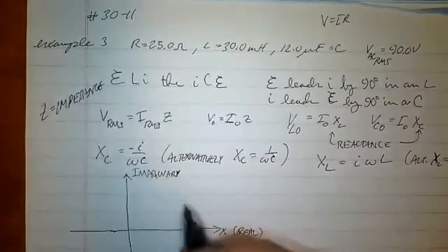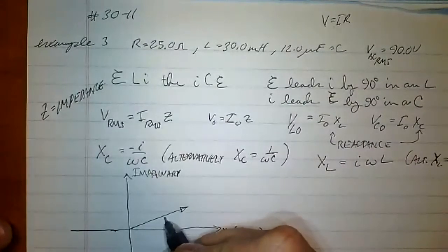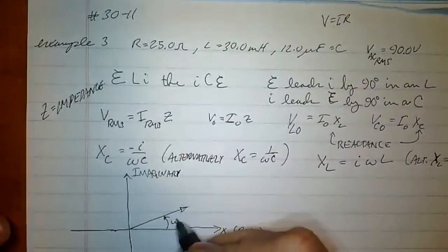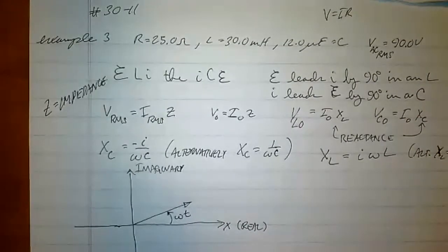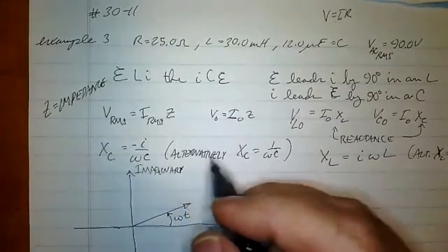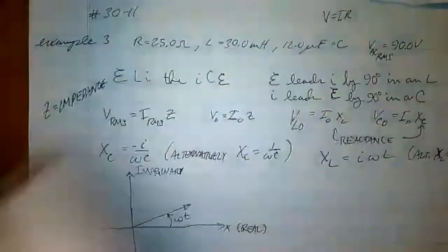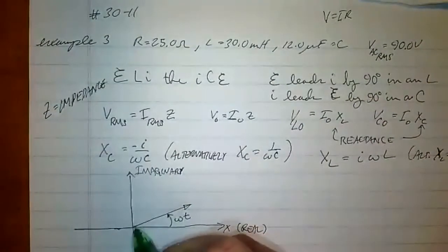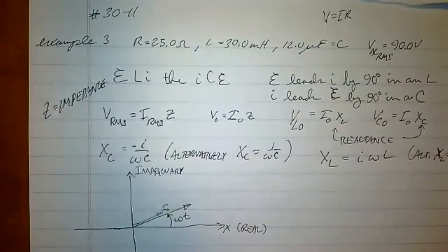Now, after any time t, this phasor diagram has rotated by an angle theta equals omega t. Now, this quantity right here, you could interpret it a couple ways. One, let me do a different color, I'm going to do that to represent I0. So that's the actual amplitude.